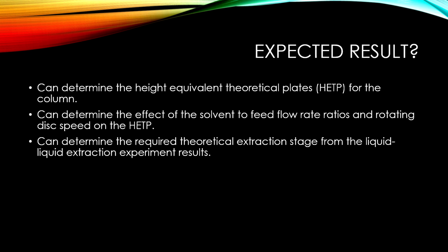The expected result: I can determine the height equivalent theoretical plates, HETP, for the column. I can also determine the effect of the solvent to feed flow rate ratios and rotating disc speed on the HETP. And lastly, I can also determine the required theoretical extraction stage from the liquid-liquid extraction experiment results. Thank you.